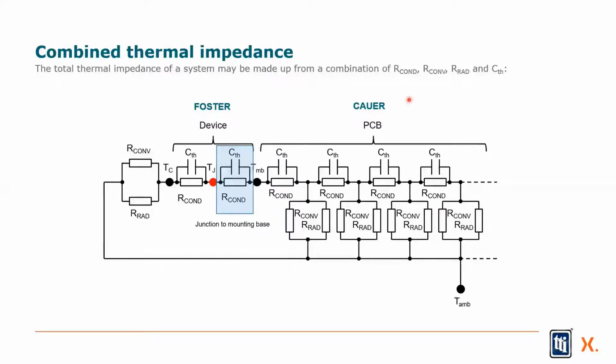If I'm lucky, and I know the Cauer models of all of my PCB, of my heatsink, of my printed circuit board, of my thermal vias, I can actually connect the two together, and I can simulate the heat from the junction of my MOSFET through the package, outside of the Nexperia device, onto the solder, onto the PCB, through the vias, out to the heatsink, out to the airflow, out to the liquid cool. I can actually simulate an entire environment using just LTSpice. That is one impressive tool that is now available.